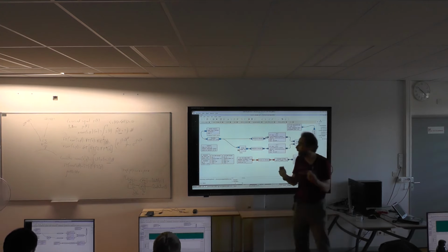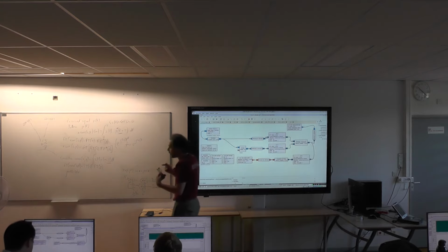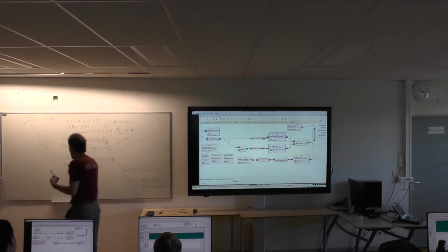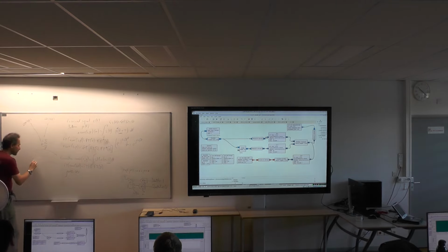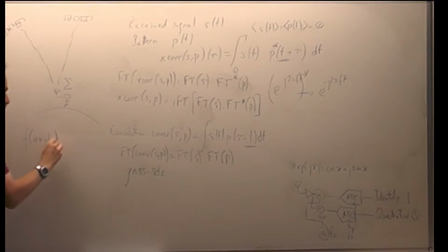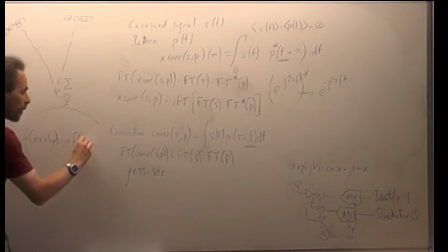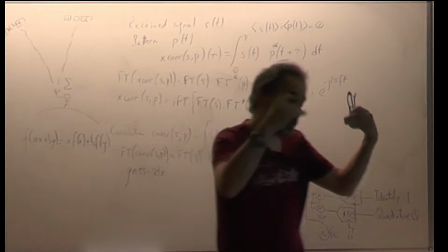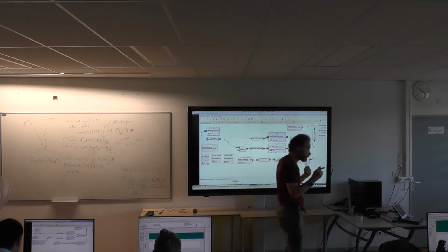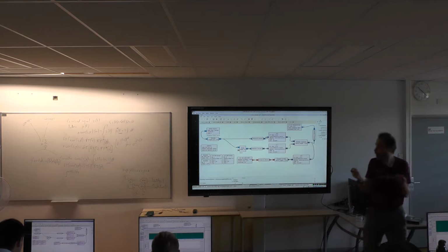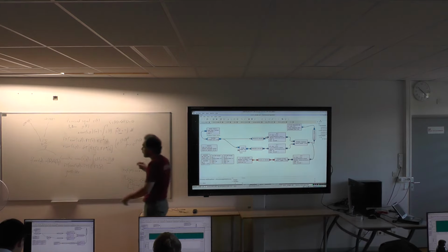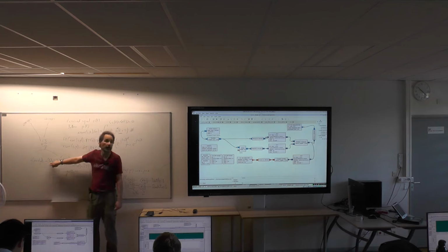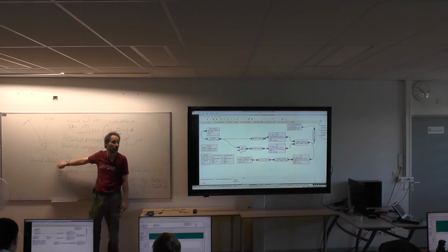We've seen that the cross-correlation is expressed as a Fourier transform, and the Fourier transform is linear. What is a linear function? A linear function means that f(ax + by) = af(x) + bf(y). So if we have a sum of multiple incoming voltages, when we run the correlation, you can actually say, okay, I got a sum of two satellites, but this is similar to processing the first satellite and the second satellite individually.